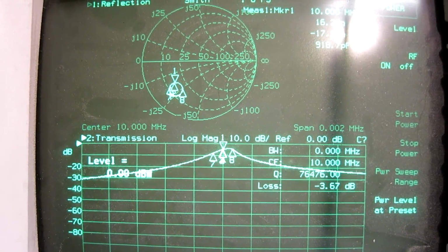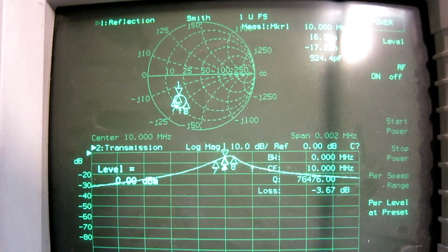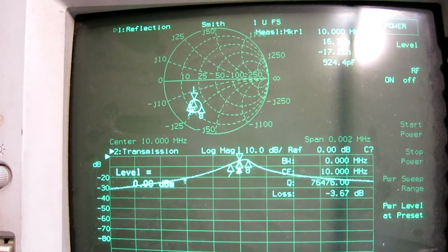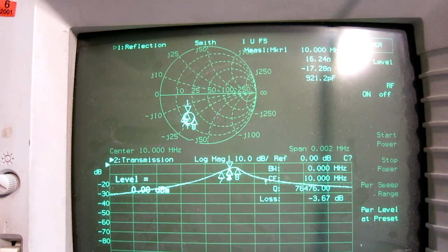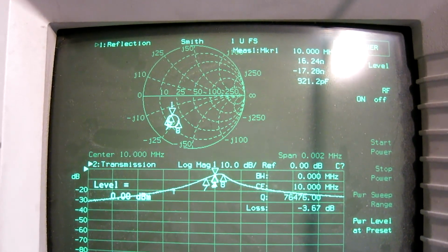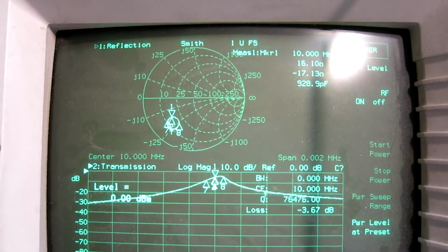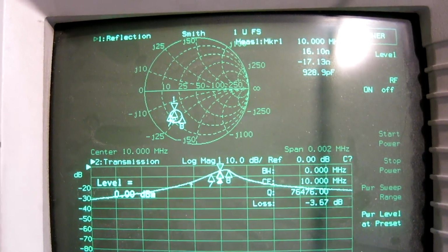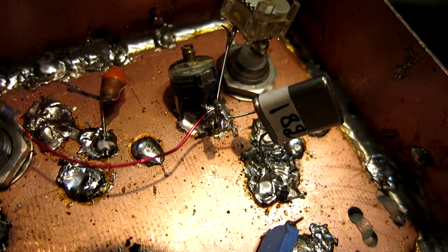So that's another advantage. Also, far from resonance, the impedance is going to be lower, which means that the noise from the amplifier will be lower because the current noise is dominating. So crystals in parallel is a significant advantage.